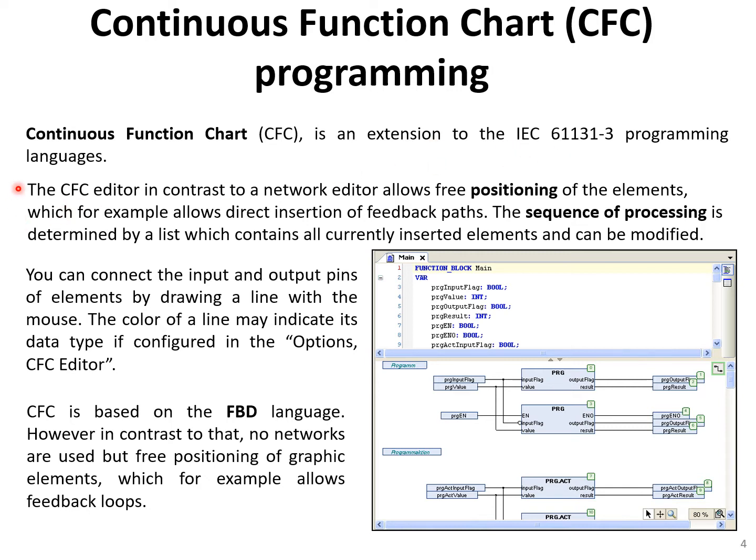The CFC editor, in contrast to a network editor, allows free positioning of the elements, which, for example, allows direct insertion of feedback paths. The sequence of processing is determined by a list which contains all currently inserted elements and can be modified. Okay, so we don't have networks as we used to have in ladder logic programming, but we have a flow box environment that is very similar to simulation in MATLAB. So if you've done simulation in MATLAB, you will find it very similar to those types of environments. And that's why, for example, you could implement feedback paths like PID controllers in MATLAB.